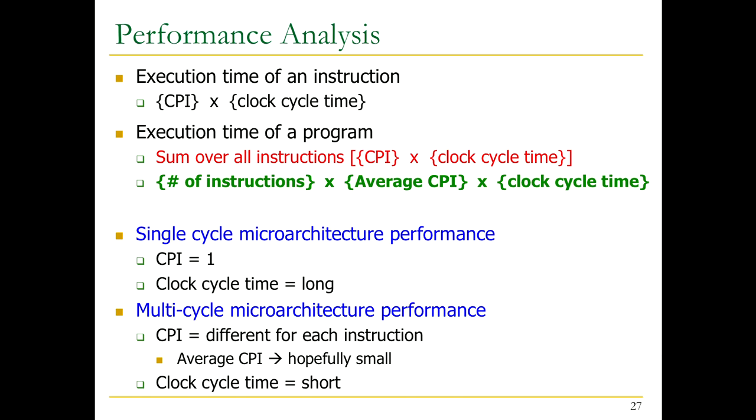We will talk about determining clock cycle time when we talk about pipelining, but a lot of this applies to multi-cycle machines also, because you don't want to make your clock cycle time too short, because there are overheads associated with register setup and hold, right? There's also jitter overheads. There's a useful part of your clock cycle, and there's a not so useful part of your clock cycle. If your overheads become dominating, you're really wasting a lot of time to latch the data into the registers, right? So too short is not always good. Too long clearly is not good. So you really need a balance.